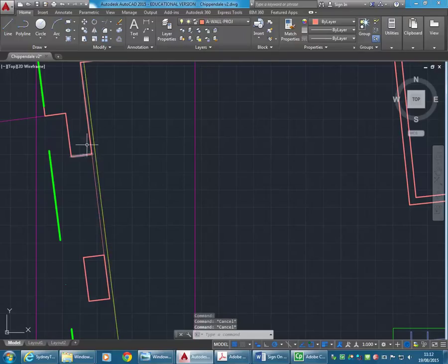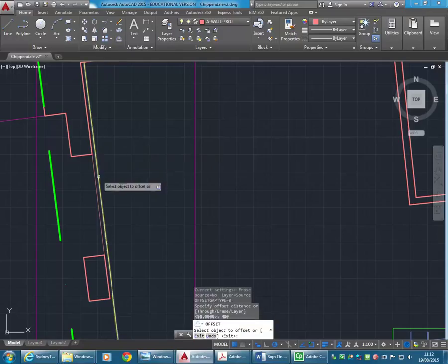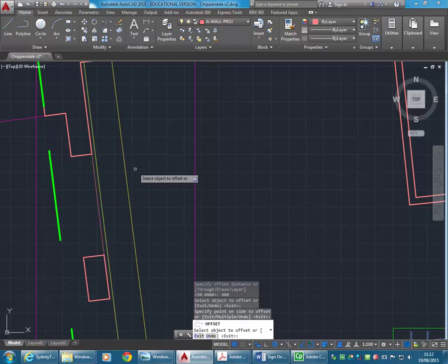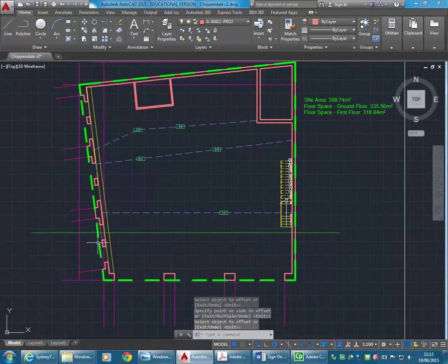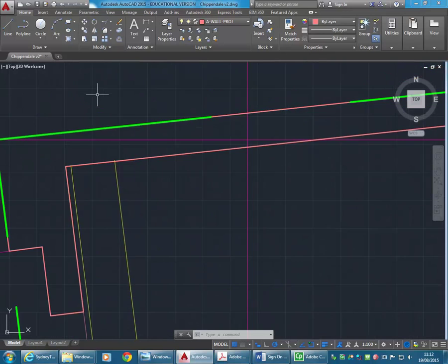And so from that line that I've got for the joist, now I'm going to offset 400. So remember, it's 450 centres, but because the joists are 50mm wide, that means the gap between them will be 400. And that's fortunate because that's the new Australian standard minimum. You could do 600 in days gone by, but now it has to be 450. I think it might even be less than that again. But anyhow, definitely 450 is fine here.